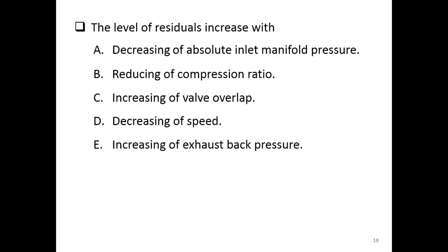If you have large valve overlap, that already affects the level of the residue, and if your engine speed is reduced, this affects the level of the residue even more. Increasing of the exhaust back pressure, because there is more time for the exhaust valve to be open together with the intake. So the pressure outside, which is called the back pressure, can affect what happens inside the cylinder, right? So the residue can hardly flow out because of that back pressure.